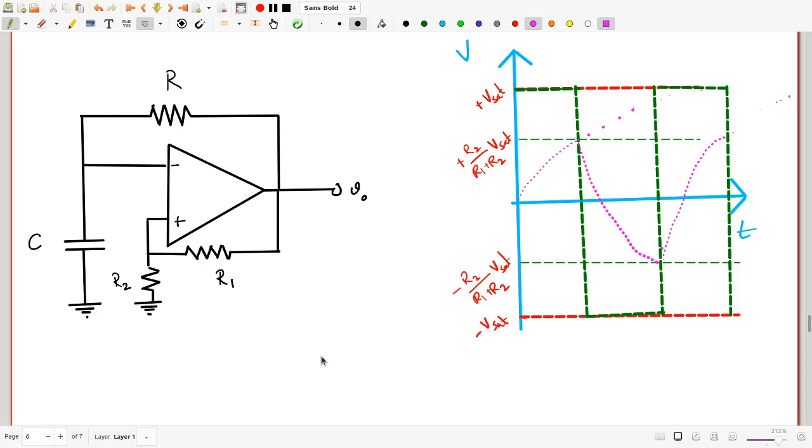But let me point out one thing. This oscillator will always produce a symmetric square wave. Okay, what will the time period depend upon? The time period, of course, will depend on how long it takes the capacitor to charge up from LTP to UTP or down from UTP to LTP. And that, of course, is connected. The time it takes will be connected to RC simply because that's what controls how fast the capacitor charges. There's a time constant for the capacitor.